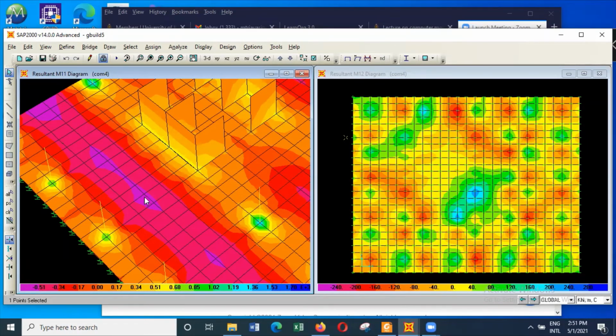You can see the bending moments are in the range of 529 and 520 and so on. This is one of the column lines. This is another column line. In between, you are getting some values like 8400 and so on. When you are designing, you will design for 522 plus this torsional moment, which can be about 80 to 90 kilonewton meters. So you will add the torsional moment and the bending moment, and then find the reinforcement requirement.